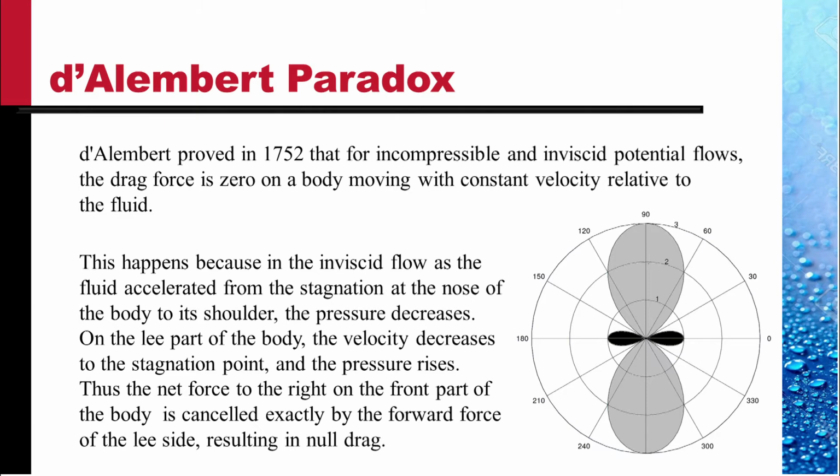Thus, the net force on the front part of the body is being cancelled exactly by the forward force on the lee side, resulting in 0 drag, 0 pressure drag. Of course, there are no shear stresses, so there is no shear drag. It was proved later that this drag is 0 on all bodies, whatever be the shape, not necessarily cylindrical or spherical.